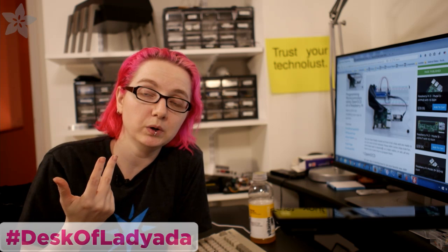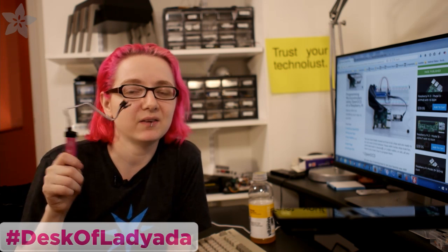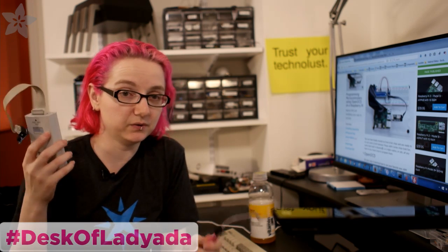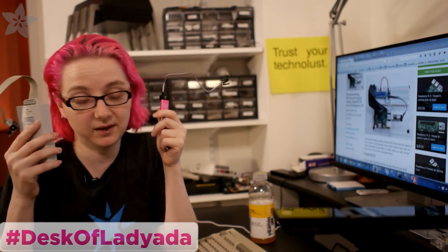There's one other trade-off, of course. If you have a board that has two SWD devices, you can't chain them, so you have to have two programmers. So you might need two J-Links, and I'm pretty sure you can only use one ST-Link per computer. So that's something you have to think about. Like we have the M0 Bluefruit Feather, and that uses a J-Link for the Bluetooth and an ST-Link for the SAMD. So I'm kind of learning this stuff, but that's fun.